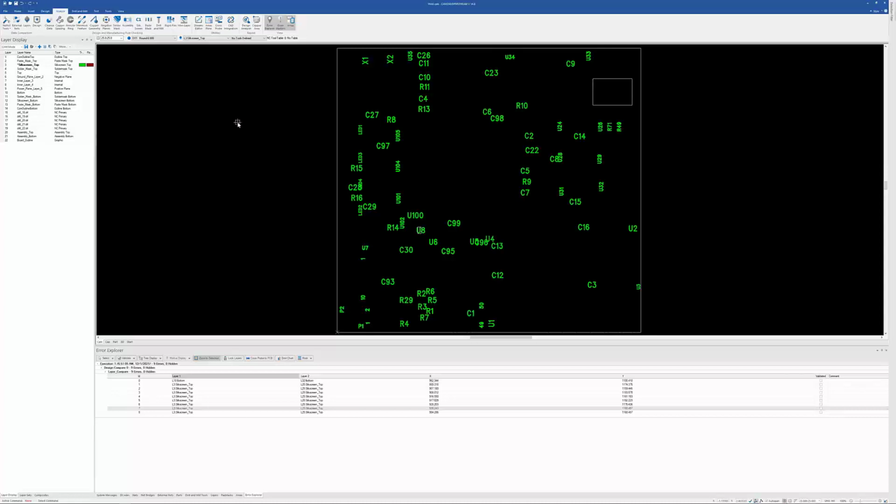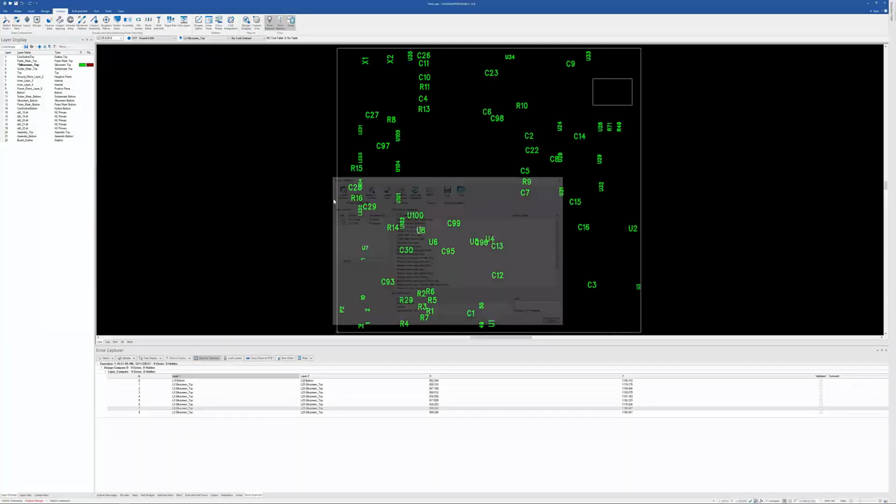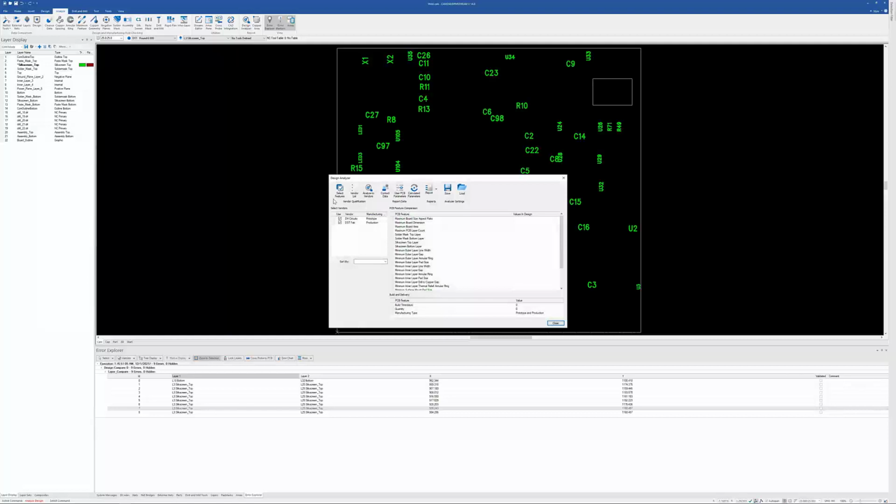I want to show you one more thing under here, and then I'm going to leave it open to questions. If you do have questions, please type those in. But we have another feature called the Design Analyzer. And it's a somewhat confusing name in that, that's all we're doing here is design analysis. But the idea behind the Design Analyzer was that originally we just wanted to extract the minimums for creating quotes. Well, that was useful for the fabricator, but not so useful for the designer. So while it created this nice report, with minimum line width, space, annular ring, copper to hole barrel, and so forth,